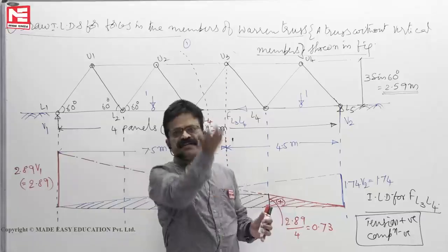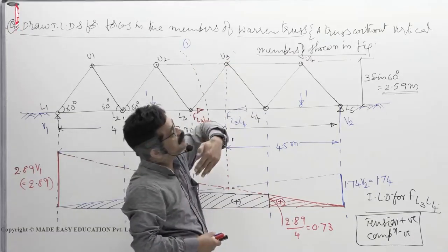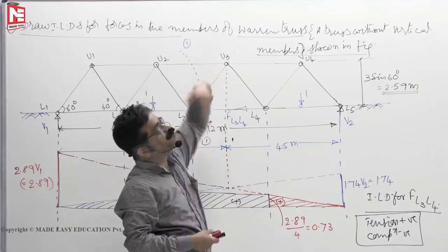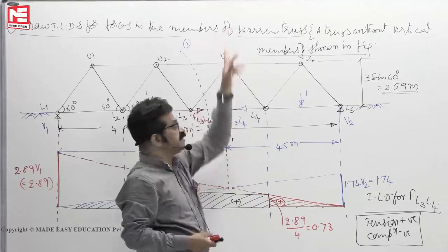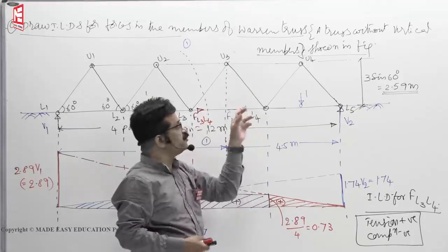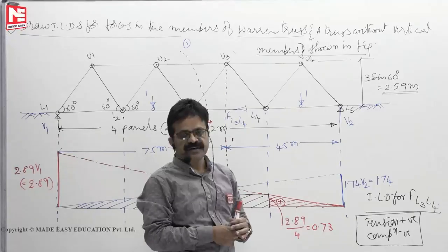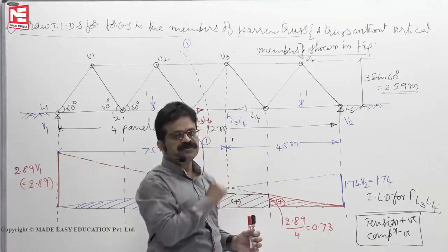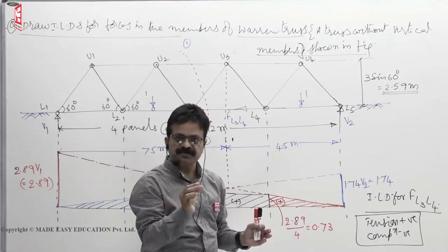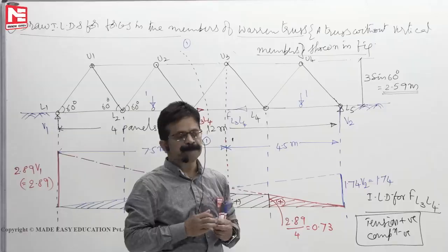Sometimes the roof covering material is there and it will be blown off, that means it is pushed up like that. In such cases due to wind load some compression will develop, but that compression is so small that instead of 400 you can go up to 350 also, because the compression force is very less.